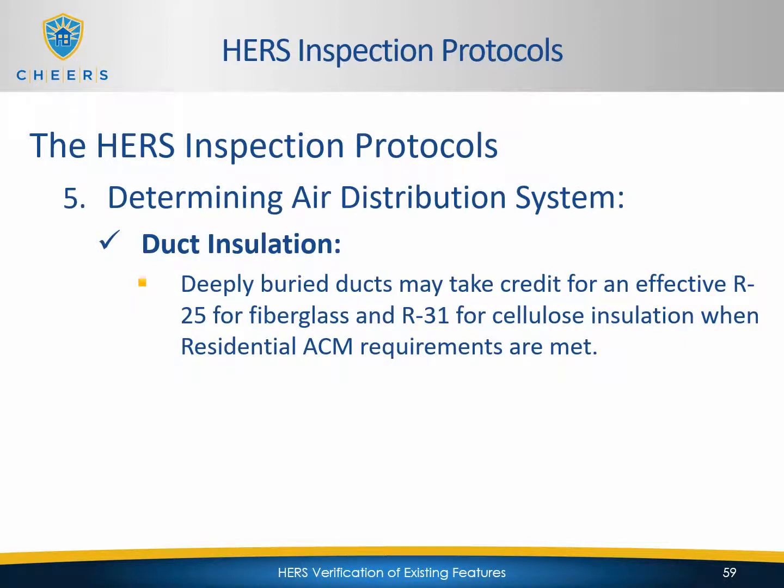Deeply buried ducts may take credit for an effective R25 for fiberglass and R31 for cellulose insulation when residential ACM requirements are met.